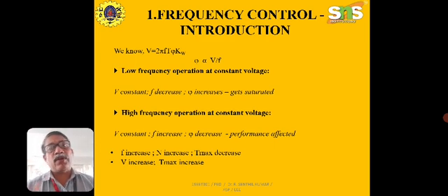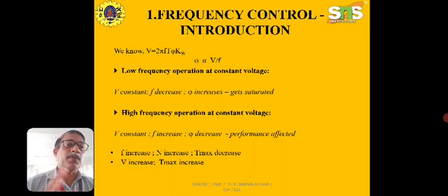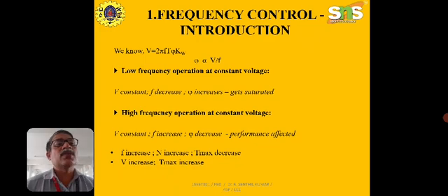Let me consider the other end. For increasing the speed, we are increasing the frequency. Again, if the frequency is increased in order to increase the speed, we have to sacrifice the performance of the induction motor, since the flux decreases.